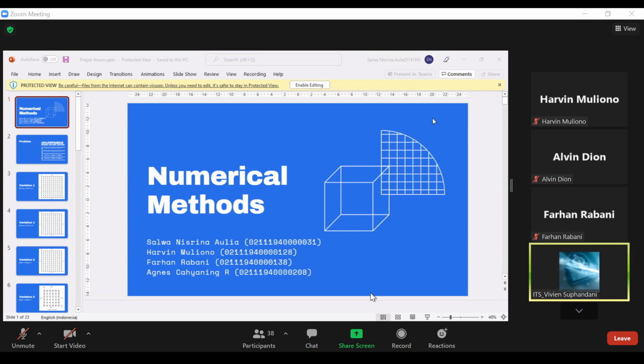And here you are using Gauss-Seidel for the iteration, for the solution method, in which the code can be used generally for all of the variations. So you can just change the temperature, for example, of the boundary, and also change the number of the nodes. Okay, so I think that is pretty good.